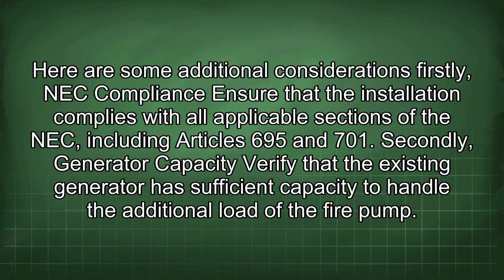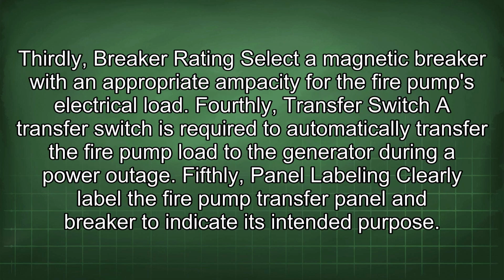Firstly, NEC compliance. Ensure that the installation complies with all applicable sections of the NEC, including Articles 695 and 701. Secondly, generator capacity. Verify that the existing generator has sufficient capacity to handle the additional load of the fire pump. Thirdly, breaker rating. Select a magnetic breaker with an appropriate ampacity for the fire pump's electrical load.